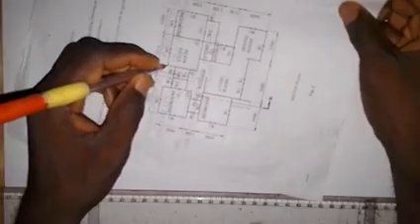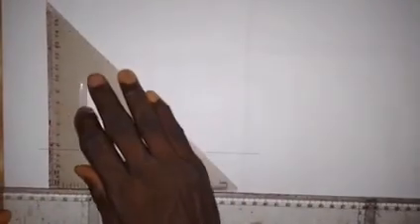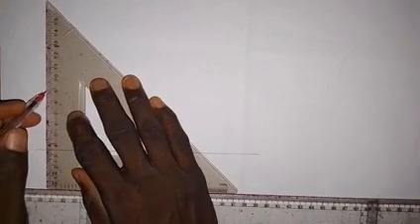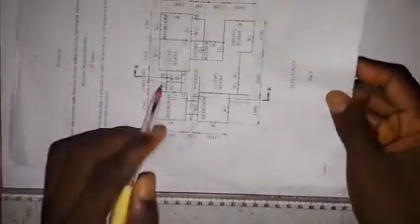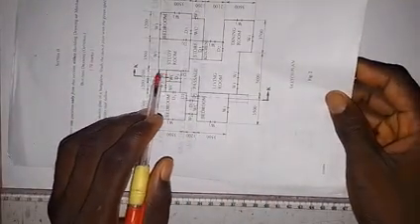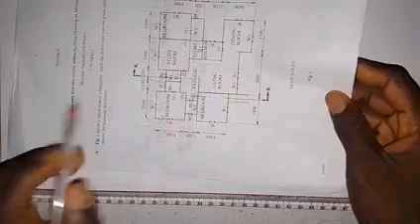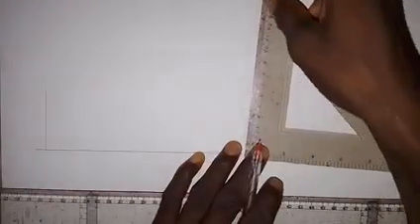The next thing that we are going to do, as I said, is to see the edge of this wall. First of all, position the edge of this wall. I will position it here like this. This line stands for the edge of that wall. And then, for us to draw this wall, the distance from here to here is 1000. 1000 divided by 50 will give us 20. So we have to take a measurement of 20 millimeters from this point to this point here.